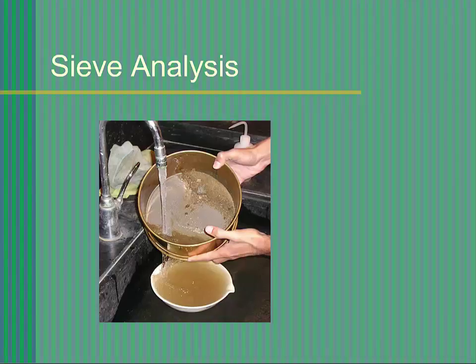However, the portion of the soil that is washed away is a representative part of the sample and must be accounted for. We will account for this portion of the sample by computing the weight lost during wet washing. Therefore, it is very important not to lose any of the sample except that portion that is actually washed through the number 200 sieve.